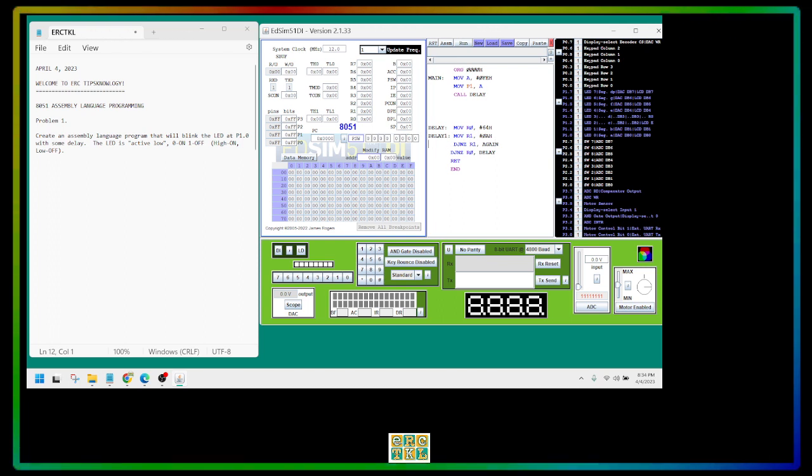And on the left side here, we can write a label again. In other words, while R1 is not yet 0, it will always be going back to again. So in other words, this will count from 10 to 0, or from A and then 9, 8, 7, 6, 5, 4, 3, 2, 1, 0. It will count 10 times, and after reaching 10 times of counting or delaying, then the 64 will be decremented again. It will be 64, and then 63, it will count by 10, it will be 62, it will count by 10, it will be 61, and so on.